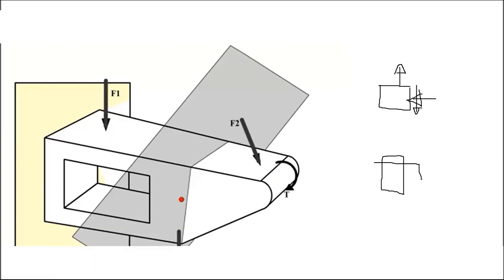So if you have the original element, right? Let's say uniaxial compression, so your element will be like this after the loading. If you have tensile loading, your element will be like this. It changed the shape of the element, but it depends on the applied magnitude and the shear stresses, right? The shear stresses change the shape like this.